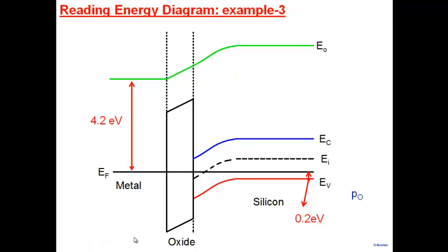What information? I know my metal's work function, and I know the doping on the other side. Do I know how much built-in voltage will form here? Well, how do I do that? We do Kirchhoff's law, Kirchhoff's law applied on the energy band diagram.